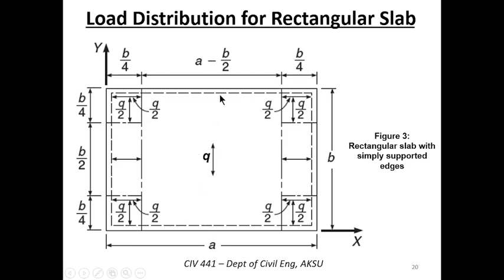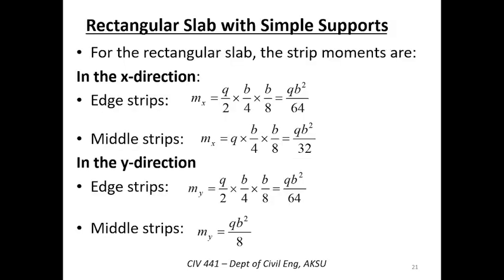And that Q is in the short span direction, nothing in the long span direction. That is at the middle strip. So take note of this load distribution because that is what will help us.